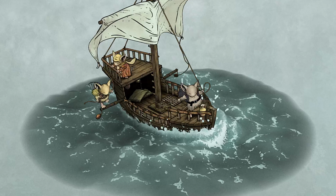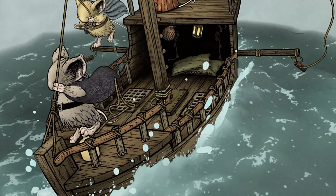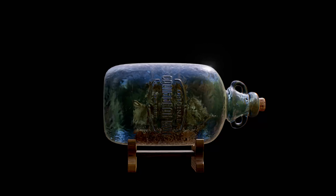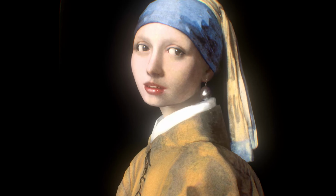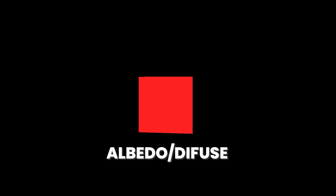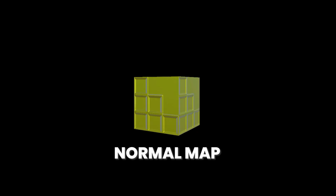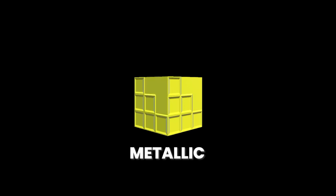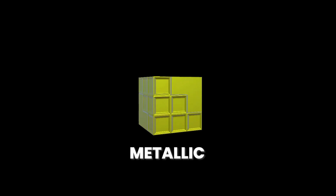Now we get to one of the most magical parts of 3D, materials. They can make a flat surface look like a cobblestone path without changing the mesh. Materials define how a surface looks and reacts to light. This is done using texture maps, each with a specific job. Albedo or diffuse, base color. Normal map, fake small bumps and dents. Roughness, smoothness, how shiny or matte it looks. Metallic, tells if it's metal or not.